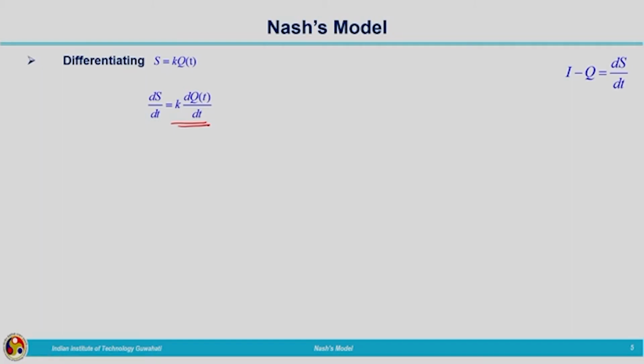This is the procedure we will be using in any of the rainfall runoff models. The continuity equation is represented by I minus Q is equal to dS/dt. The complexity comes in the storage function, which is represented by the transfer function. This S can be considered linear or non-linear, depending upon the knowledge about the system, and we can derive the mathematical expression related to that particular system.